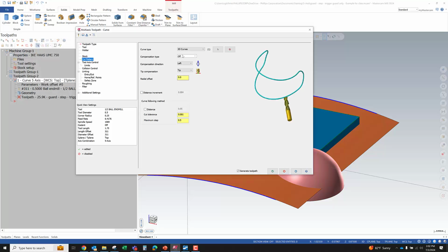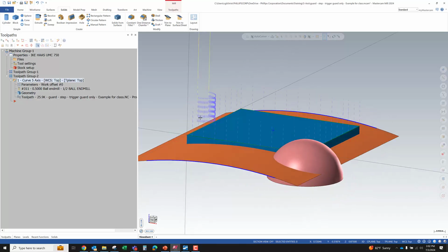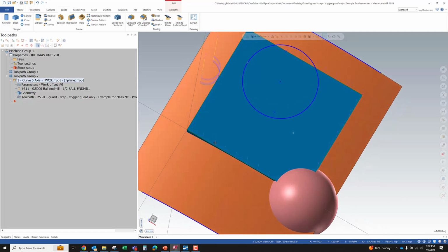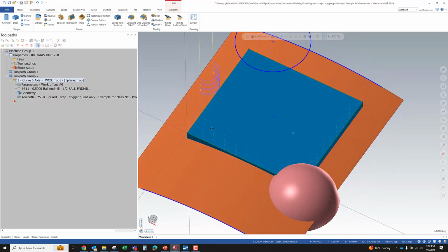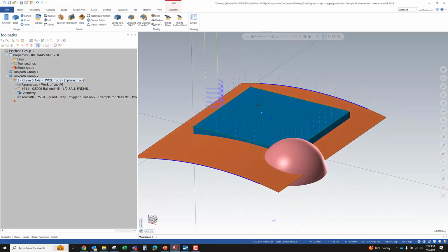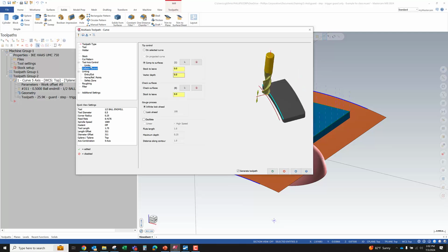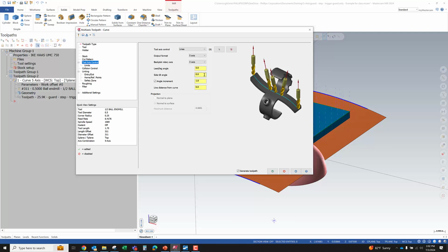So I'll say OK. Everything's copacetic. But the reason why that can matter is that it will control where your exit is. All right. Now what happens if I go to my tool axis control and I say, hey, give me 35 degrees of side tilt?